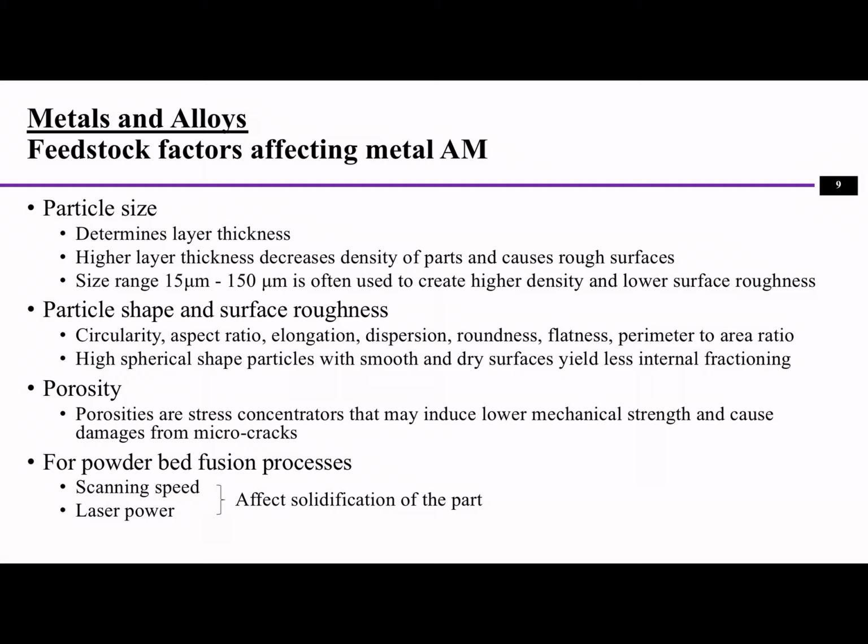That's the place where a lot of stresses are going to concentrate. And if there is a lot of porosity, then it will reduce the mechanical properties, for example, the strength, right? And it will also easily get fatigue. For example, it gets damage from macro cracks, and those cracks will get bigger and bigger over time.